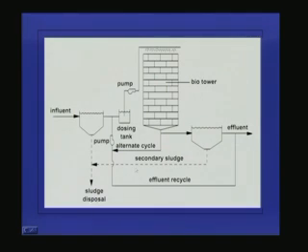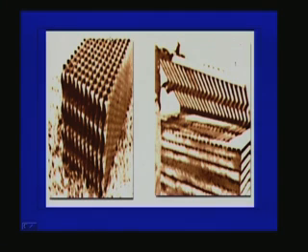And if you don't want to have this type of recycling, we can even have a recycling from here itself. Instead of increasing the secondary sedimentation tank volume, we can have an alternative recycling from here. So it's all depending upon how we want to operate the system, but either this recycling or this recycling is not going to affect the performance of the system drastically.